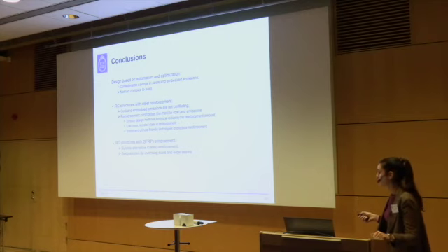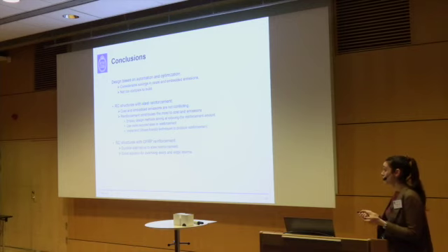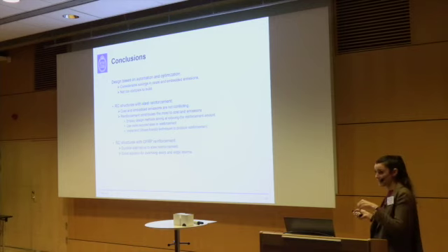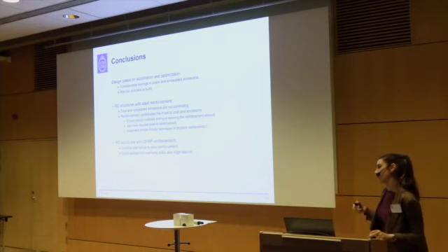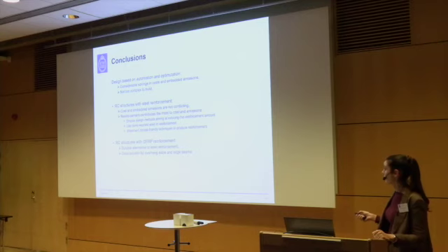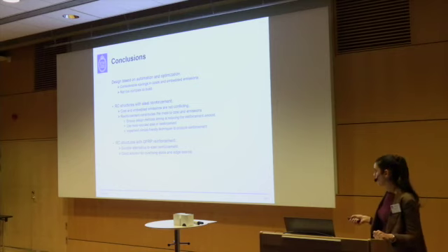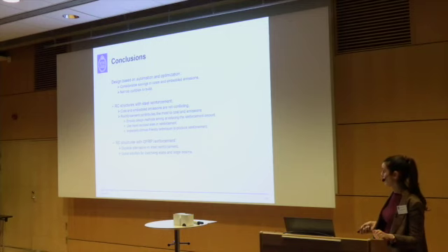So we should try to push our designers not to oversimplify, but to actually design using methods that minimize the reinforcement. We should try to use more recycled steel within our reinforcement. And we should also invest a bit, not only in the research to replace cement, but also how can we get better climate-friendly steel reinforcement. And if we can't, or in parallel, we should try more durable and less impacting materials, such as GFRP.